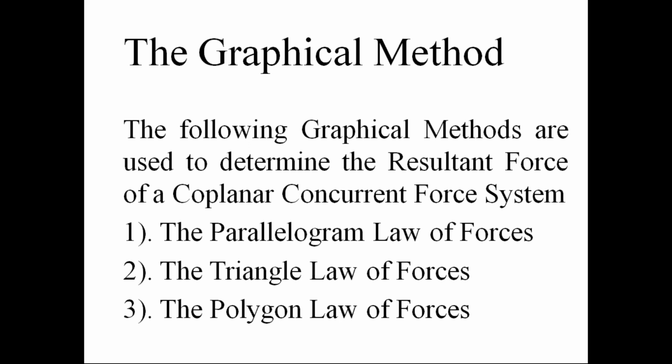R is equal to the root of P square plus Q square plus 2PQ cos theta. Please remember that from the intermediate junior level. The same parallelogram law we are going to apply in this coplanar concurrent force system. Since here we are applying the parallelogram law for forces, we call it the parallelogram law of forces. You might have studied the triangle law of vectors and the polygon law of vectors also in the lower classes. The same we are going to study in this graphical method for forces.